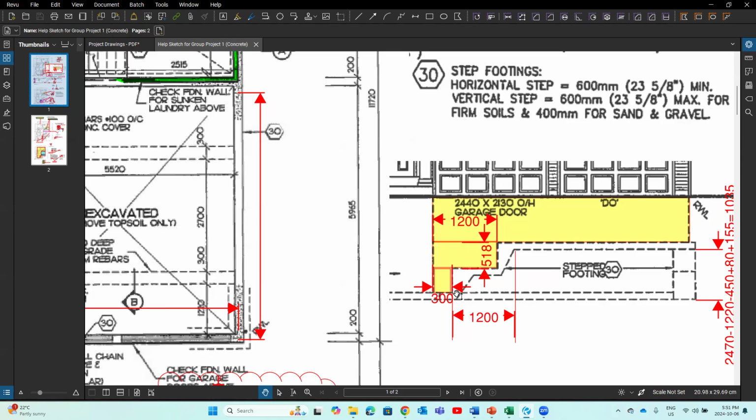Also extra labor to do this, to cut the shape like this, right? So this part of the formwork for the footing, it's more expensive than the formwork this side. For example, this formwork here, it's around, let's say, $15 per meter, okay, or $20 per meter. But here would be $20 or $25 per meter around here. So I need to separate them.